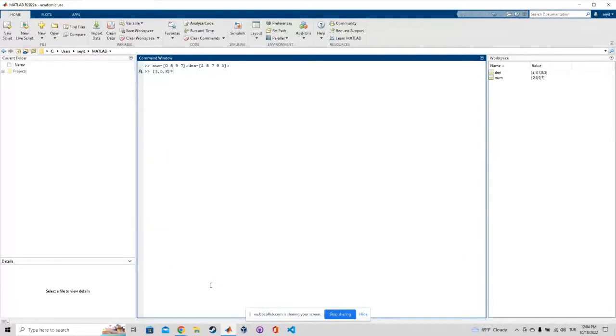And then you hit equals, write tf2zp, and you add zeros and poles, right? TF means transfer function, Z and P mean zeros and poles. And tf2zp, transfer function to zero-pole, you transfer it, and then you just open your parentheses, numerator, comma, denominator, all right? And that's it. When you hit enter, it will give you your zeros, your poles, and your gain. All right, guys?